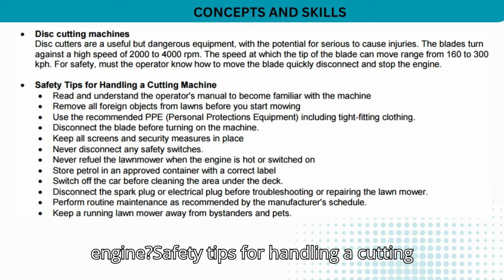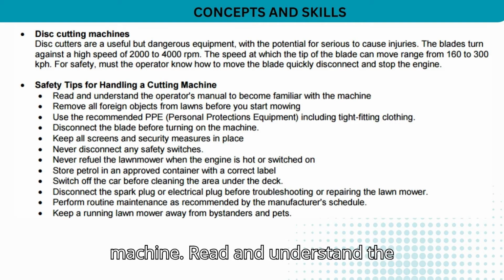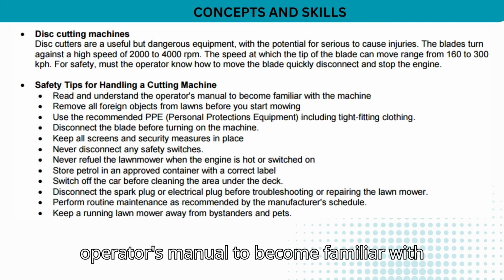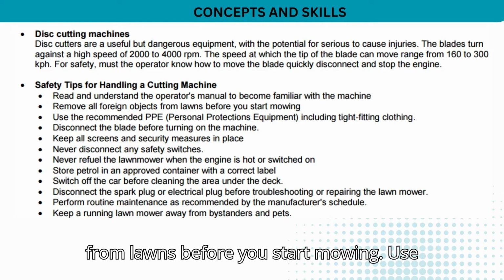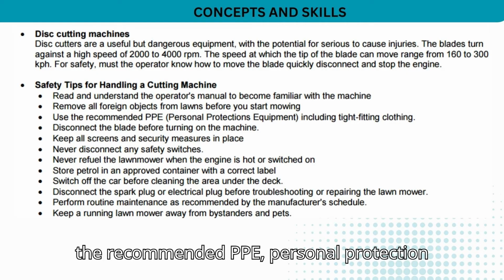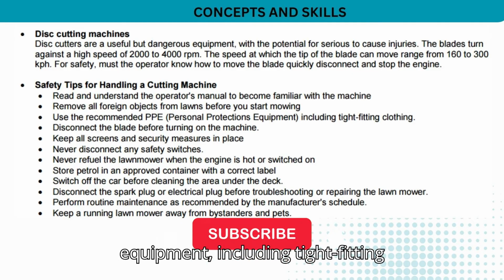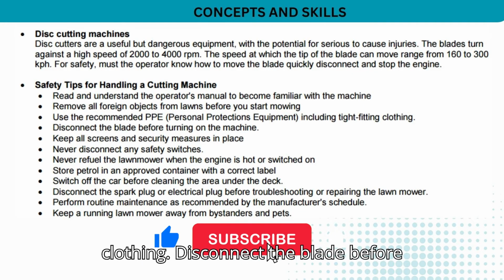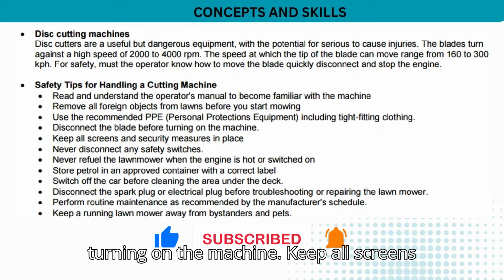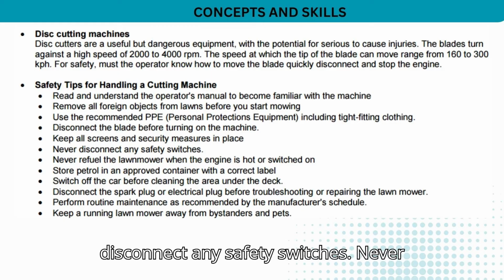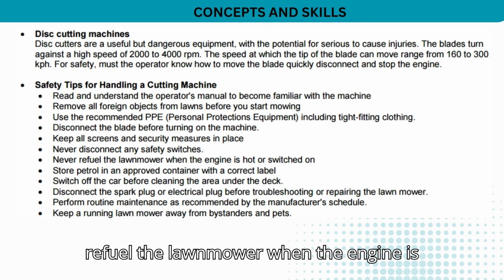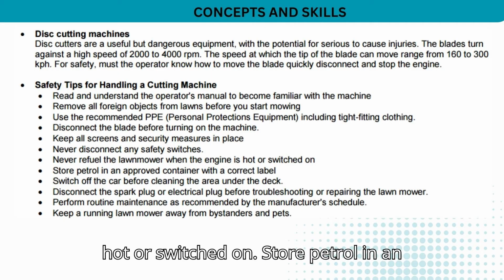Safety tips for handling a cutting machine. Read and understand the operator's manual to become familiar with the machine. Remove all foreign objects from lawns before you start mowing. Use the recommended PPE, personal protective equipment, including tight-fitting clothing. Disconnect the blade before turning on the machine. Keep all screens and safety measures in place. Never disconnect any safety switches. Never refuel the lawnmower when the engine is hot or switched on.